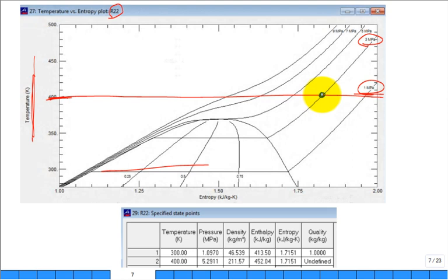Now, if I put it through a pretty good expansion through a turbine, I cannot drop it below that pressure. Why? We just had that discussion. That's my condenser pressure. Where is the exit state going to be? Here, or maybe if I have some irreversibilities, it'll move up. Is that a good design choice to bring it out at this state?